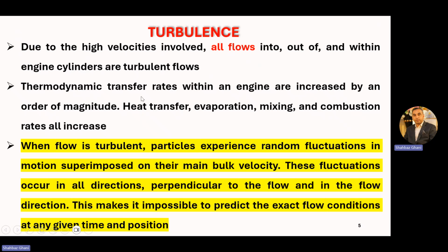Thermodynamic transfer rates within the engine are increased by an order of magnitude if we have that turbulent flow. Heat transfer, evaporation, mixing, and combustion rates all increase due to this turbulence phenomenon. Now, when a flow is turbulent, particles experience random fluctuation in motion superimposed on their main bulk velocity.